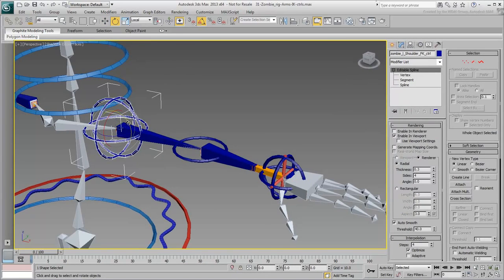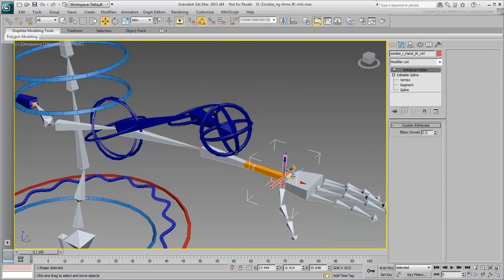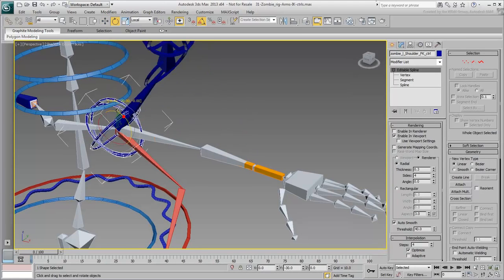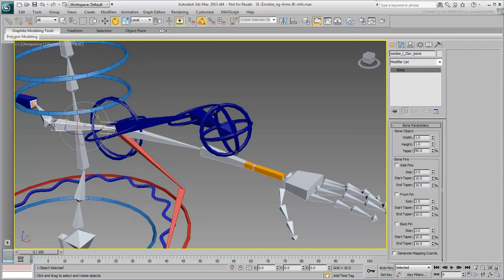You now have manipulators to control the FK chain and the IK chain. However, neither of these two chains is affecting the character's geometry. The geometry is skinned to the gray bones that still need to be blended in IKFK modes. Before you get to that, however, there's one more controller that is needed, one to handle the clavicle. Whether you lift the arm using IK or FK, you still need to compensate with the clavicle, otherwise you get a pretty bad and unnatural motion.